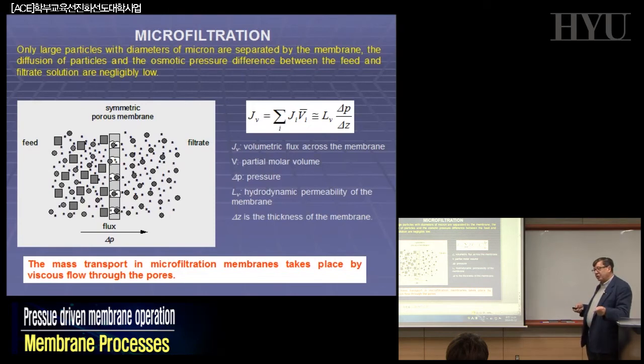In membrane distillation, you have to find the appropriate thickness, because you have another problem. You have heat transfer across your membranes. And so if you want to decrease the heat transfer, that means increasing the energy efficiency of your system, you have to increase the thickness.